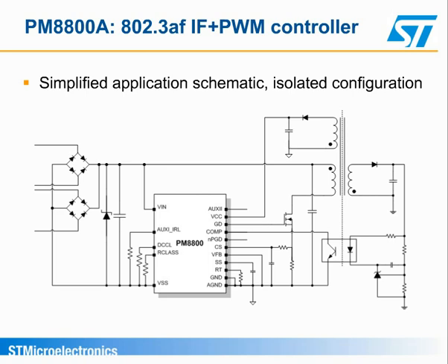For the DC to DC converter, the soft start duration and the switching frequency are set using the SS and RT pins. The current is sensed on the CS pin, while the loop is closed on VFB for a non-isolated topology or on comp for an optocoupler-based topology. GD is the primary side MOSFET driver. VCC is the pin that supplies the circuit.